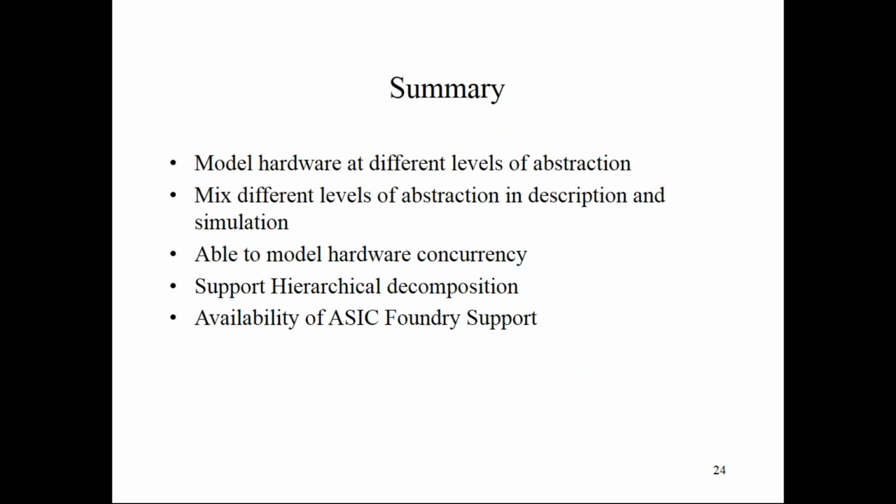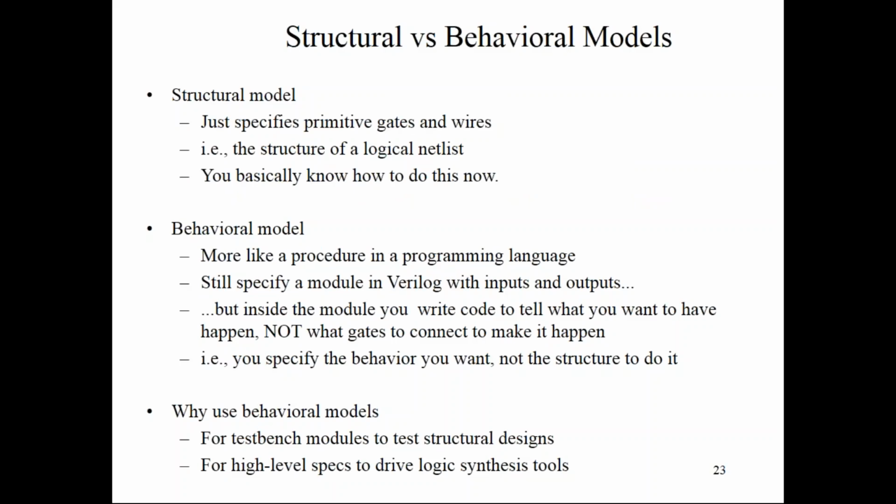So this is a summary of today's lecture. We have seen the different levels of abstraction. Another modeling style is data flow modeling. Besides behavioral and structural, in data flow modeling we just describe the Boolean logic expression with the assign keyword.